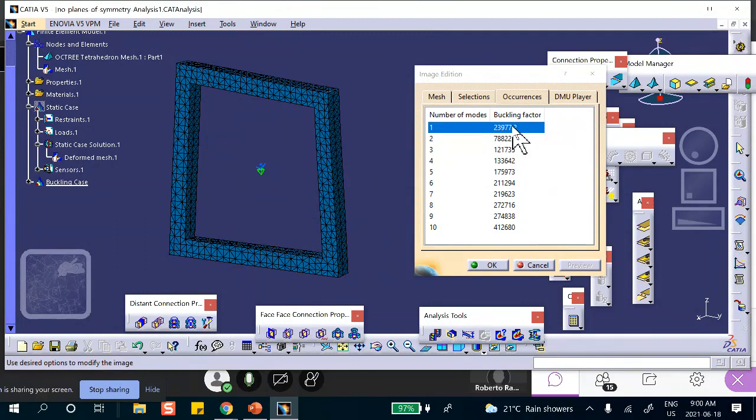You might say, whoa, my God, 24,000 pounds. That's impossible because 24,000 pounds is a gigantic load. That's because, remember, this is a non-conservative estimate. It says, don't worry about anything more than 24,000 pounds. But real life is going to make this thing buckle at that mode, for example, well below 24,000 pounds.